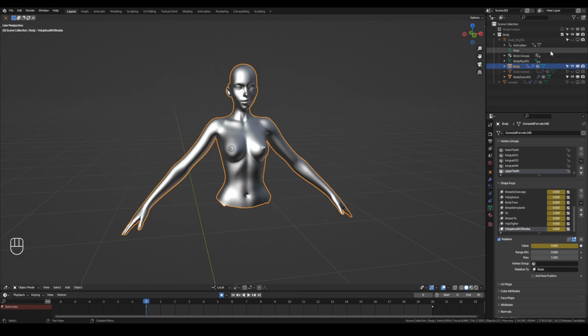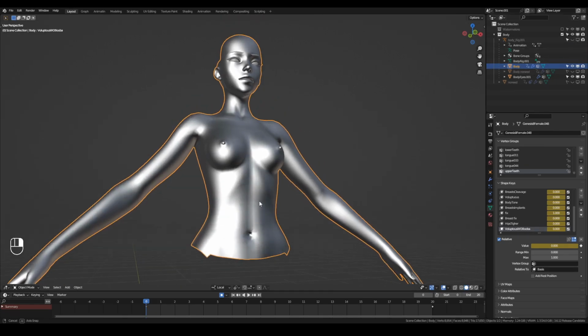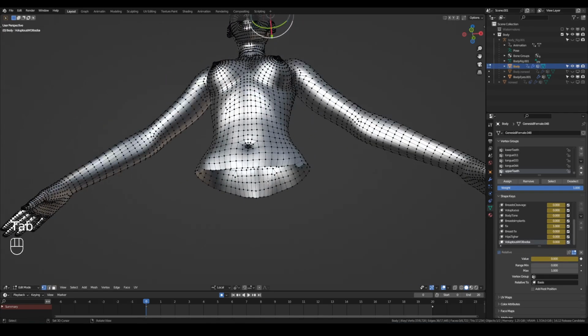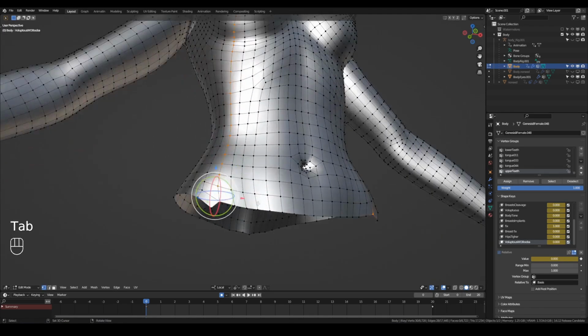First of all, we need to close all holes in the model. This is needed to make a good collision model for any liquid, or sometimes when you want to simulate cloth over a body that is being affected by jiggle sim, which we're doing in this tutorial.